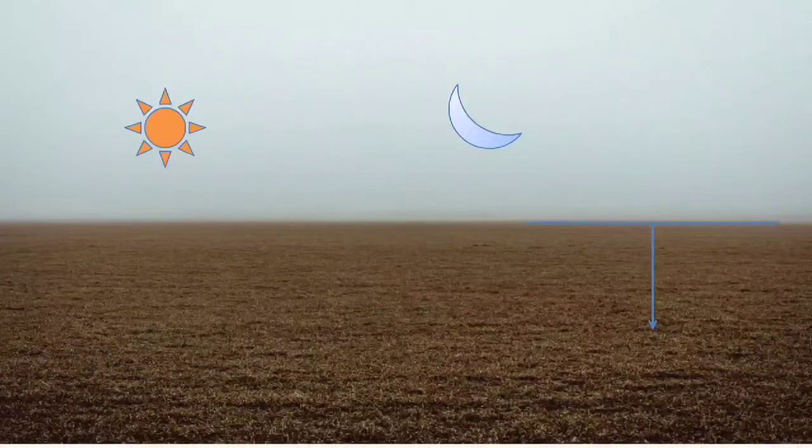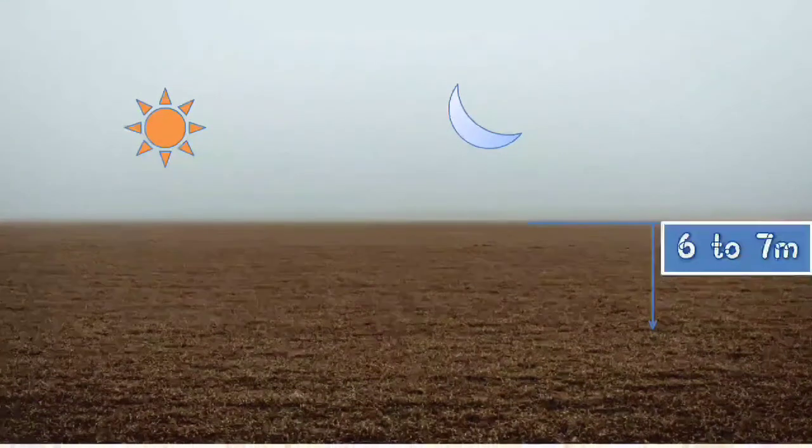It is seen that this fluctuation in ground temperature reduces as we go below the ground. Measurements show that the soil temperature below a certain depth remains relatively constant throughout the year. This is because of the thermal inertia of the soil. Therefore, we can say that at a particular depth, the soil temperature is always higher than the outside air in winter, and it is always lower than the air outside during summer.